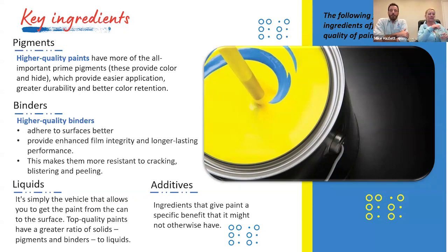It was taught to me years ago, paint doesn't know when to be a primer or when to be a top coat. It goes on the wall or the surface and it dries. Now we have top coats that have very good adhesion ratings, and that's essentially how we would market a paint and primer in one. It's always important to have them categorized separately. That way we're addressing the specific needs of the surface or the substrate, and it could require a certain primer to better benefit. If it's a wood or a chalking stucco surface, an all-in-one paint and primer may not have the certain benefits there.